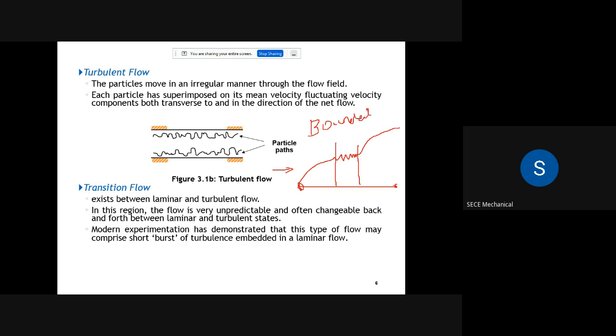Depending on laminar, turbulent and transition flow, they will form a certain set of boundary layers. So the boundary layer concept is very, very important while studying laminar flow, turbulent flow and transition flow. You must study what a boundary layer is, and what boundary layer separation is. Below the turbulent layer, there is what is called the laminar sublayer.